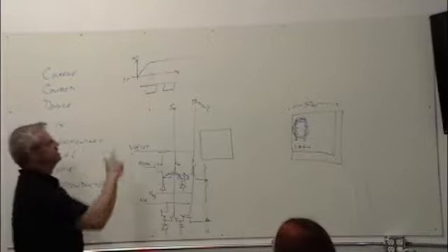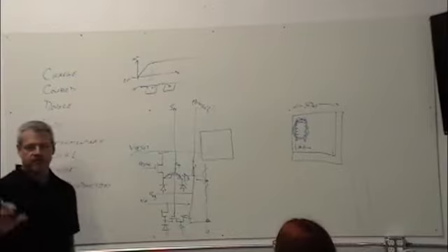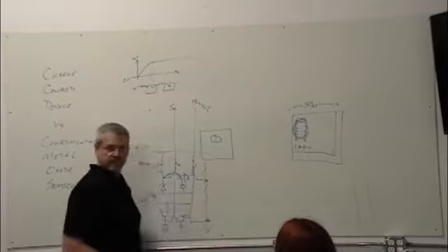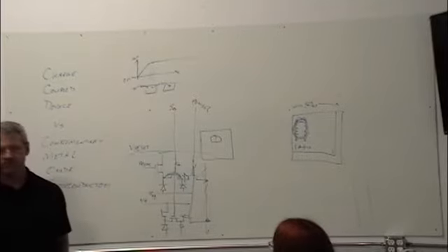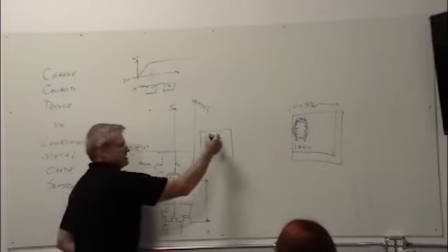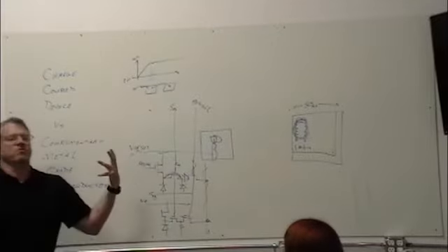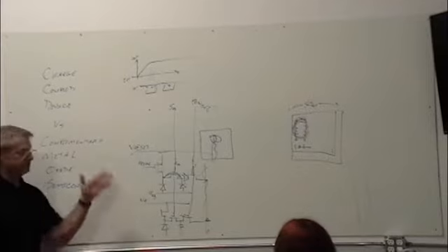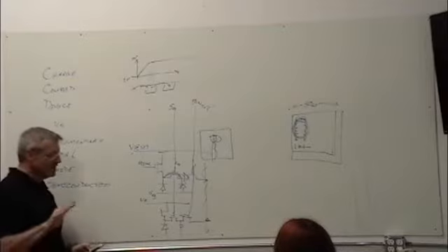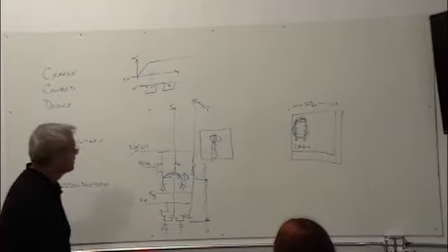And what's worse is when you hit that 100%, the reason it's flattened off is because now the charges are going over the neighbors. So if you've got a really bright source on a CCD, you'll see what's called blooming. And you can see it on some of your cameras. If you turn down some of the signal processing and point it at reflections on the water or whatever, then you get this big streak like this. It's because they're blooming out into the neighbors and it's smearing out because there's so much charge there, it can't get rid of it. You see it sometimes, especially on older cameras. The newer cameras, you don't see it so much. I still see it every now and then just because I know what to look for, right? Oh, hey, there it is. I know what's going on there.